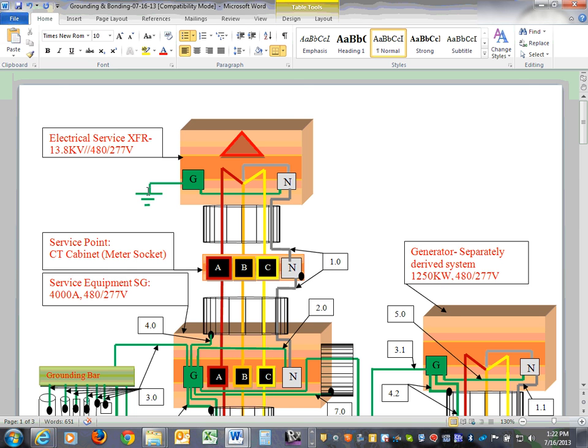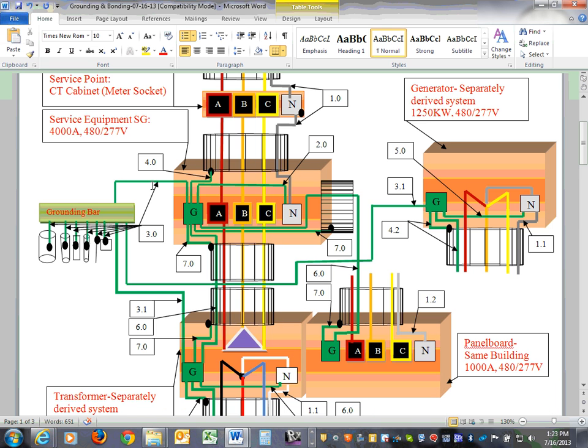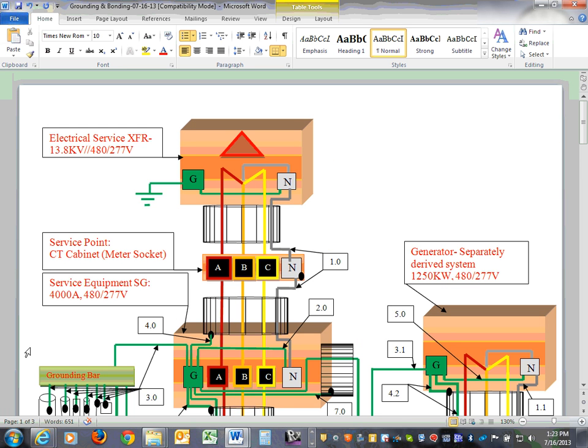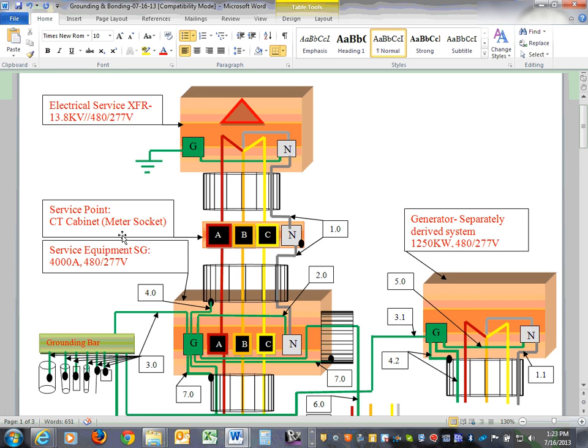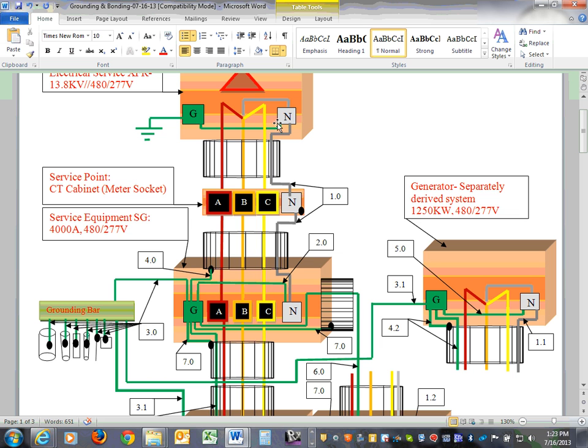And we don't depend on just one. Can you guys see, here we're tying to the ground, and also we're tying to the ground here. So now the two systems are tied together through the ground as well as through the neutral conductor. Can you guys see that the neutral is also acting as bonding between the system and the equipment, right? Because I'm bonding this to this. If you come from here, go through here into the main bonding jumper, into the neutral, all the way to the ground again, it's like a parallel path.